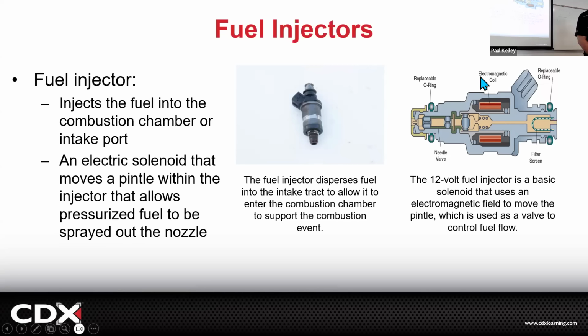All right, but what if the injector needle and seat was stuck and the injector was dripping fuel into the cylinder all the time? Do you think you'd smell that? Yeah. Exactly, right? So an electrical failure, no fuel smell. A mechanical failure, if it's leaking, fuel smell, yes. But let's just say that this was clogged up with rust. I don't think you'd smell a thing. The injector would even click, but it would not spray any fuel, right?